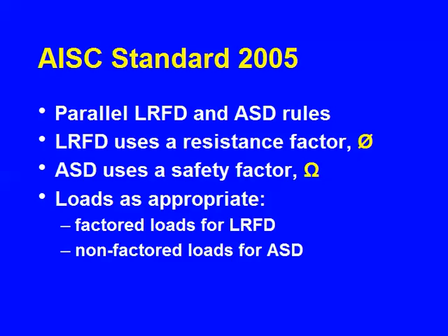And you use loads that are appropriate for the system. The LRFD system demands that you're going to work with factored loads. You're going to say, there are the loads, I think, but they could be greater. Those are the factored loads. Somebody has to tell you what the load factors are. You can't do that reasonably on an individual basis. And in the other system, allowable stress design, we don't increase the loads. We handle it differently, to come on another image.